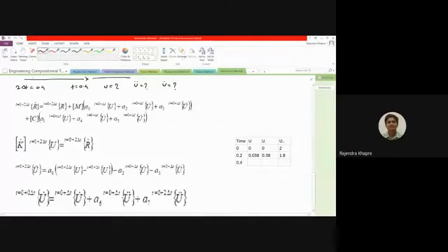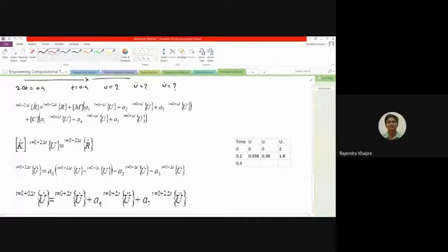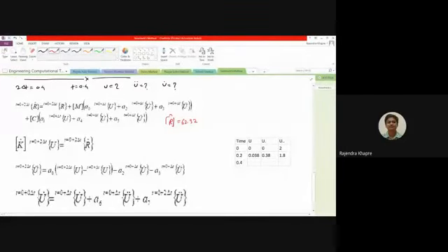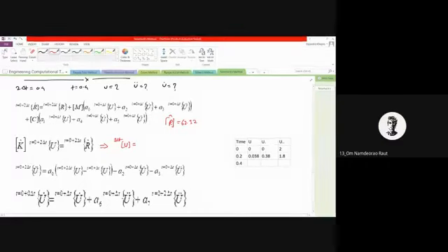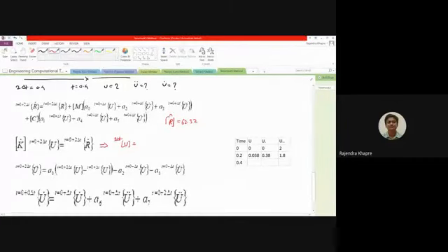So this value, your effective load vector R, is coming out to be 62.32. Okay. And how about this one? If you solve this, what is the displacement at 2 delta t? Anybody? Sir, 0.148. Let me check. Yeah, 0.148. Correct. So here you can write 0.148.